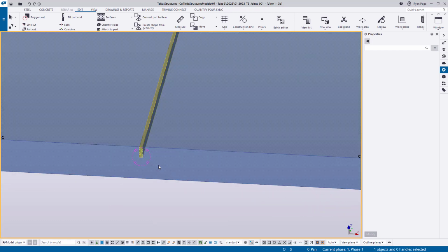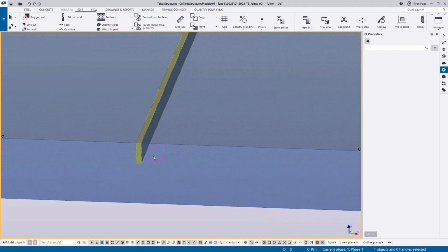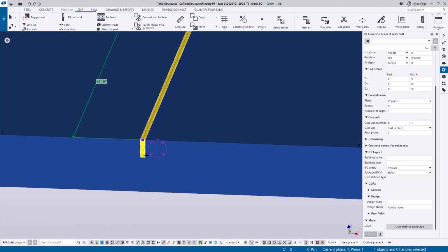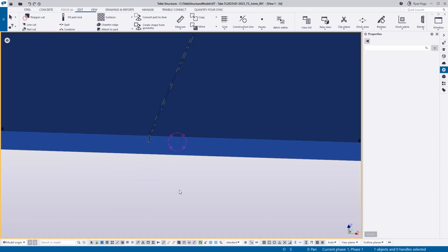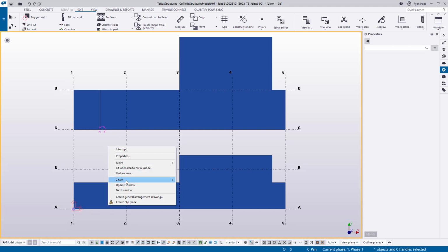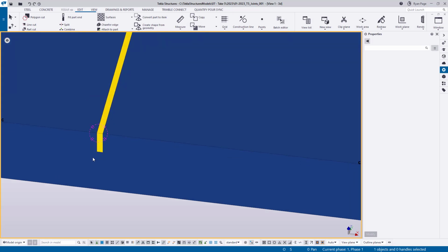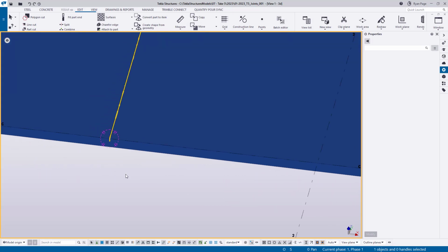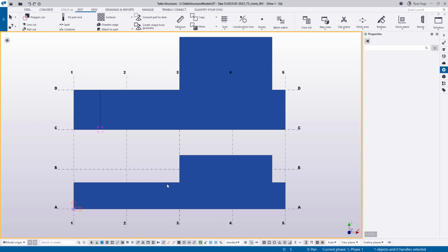And so that's going to go ahead and create a cut for us. We can turn things transparent, and we can see the beam, the joint that we have made. We can right click and hide it, and you can see the cut. And it's part of our slab. This will update our volume, and then we have an actual physical piece that we can also quantify. That means we can call it something, we can get its linear footage and its dimensions, and if you needed to, surface area or volume, and then you're able to go ahead and continue to repeat this process or copy it into place wherever you see fit.